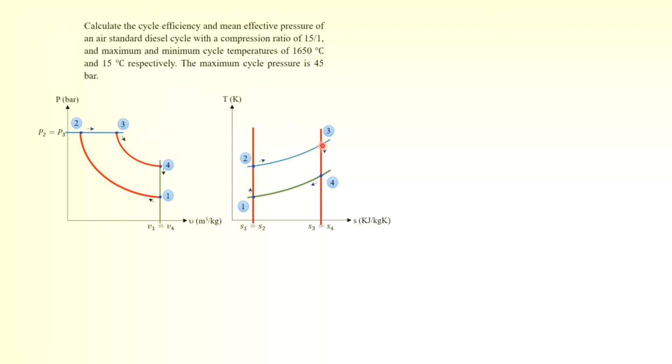So when you refer to state point 2 to 3, which is constant pressure, and also it is a heating process or heat supply, which you can see based on this arrow here is an increasing entropy direction. And then 4 to 1 here, which is the constant volume process. Okay, so that is the decreasing entropy. So this is the increasing entropy and this is the decreasing entropy. So you have heat supply here and heat rejected to the sink. Okay, and the cycle goes in clockwise direction. So I can note here.